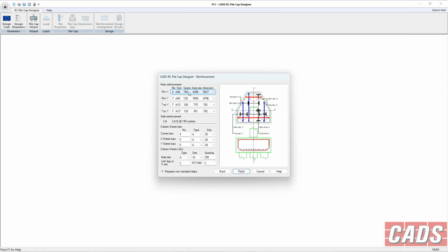So here are all the rebar solutions based on the sizes of bar that are in the default parameters. And we've got from 10s up to 40s here, so we can change now to suit the fact we want only 25s and we don't care how many. We've also got this problem here where the 12 is going to have an unusual bend. It can't really fit in there, so you can change the bar size for that, but it's entirely up to you. You can choose whichever option you would require.